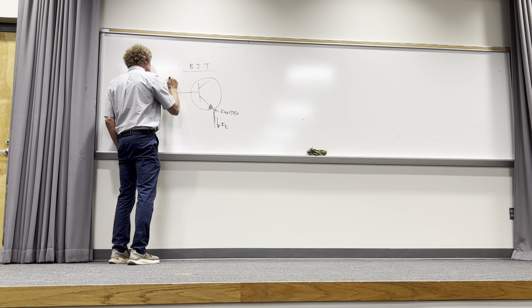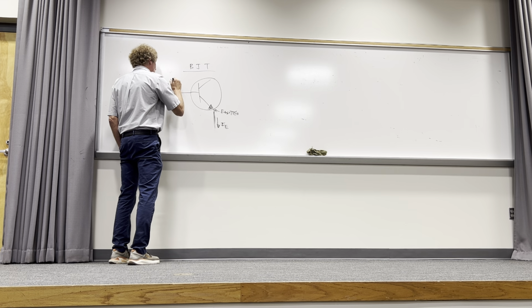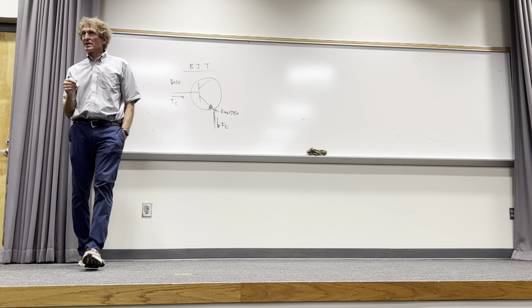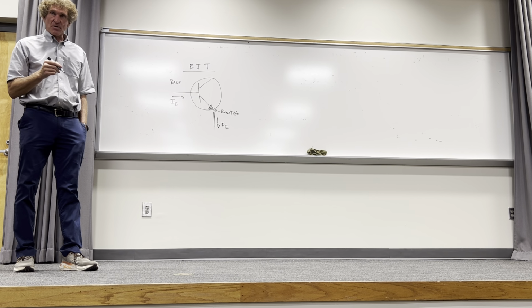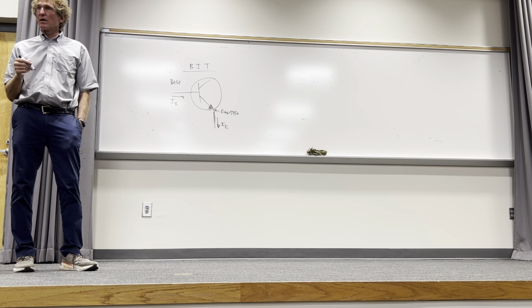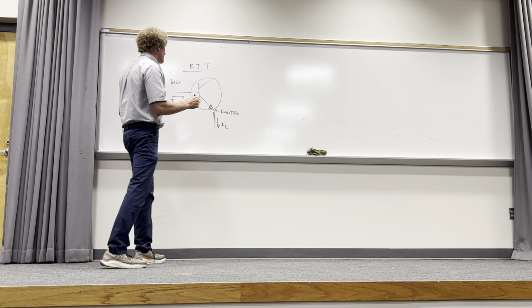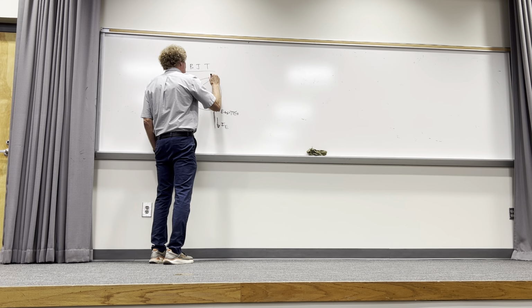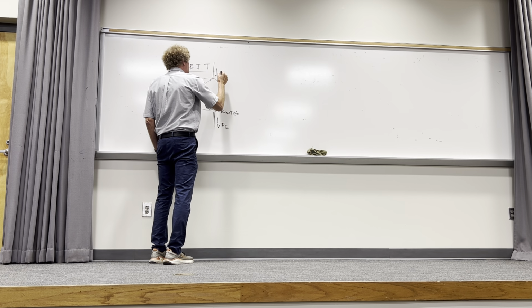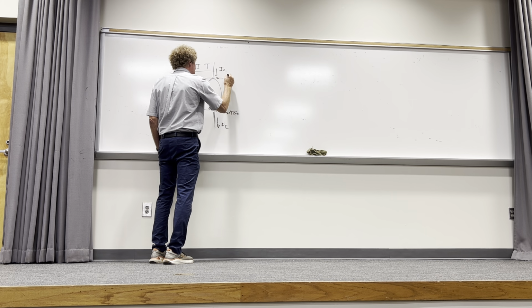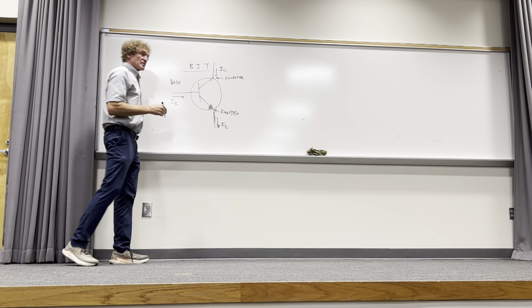This is called the base. And current flows into the base. Whenever you see capital letters, they denote a DC, or continuous current. And when you see a small ib or small ie, it has to do with AC current. Then you're going to have a current flowing down here, IC. This connection point is called the collector. That's what they look like.